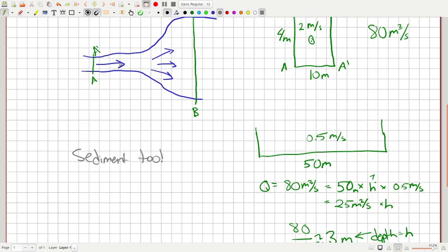As you might imagine, if this flow is really deep, it's going to be able to carry a lot of water and a lot of sediment with that water. That sediment is going to be moved along by the high shear stress that this flow is placing on its bed. But as the flow becomes shallower and expands out here, it's going to be significantly decreasing its capability of carrying sediment.